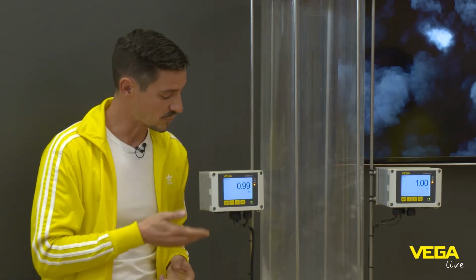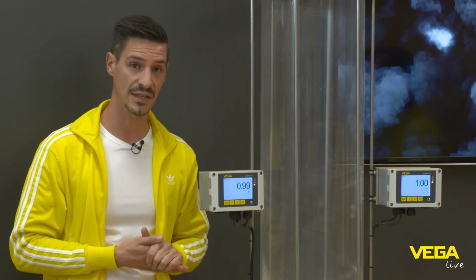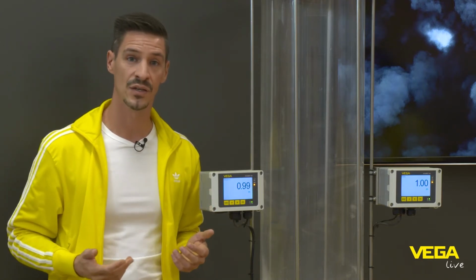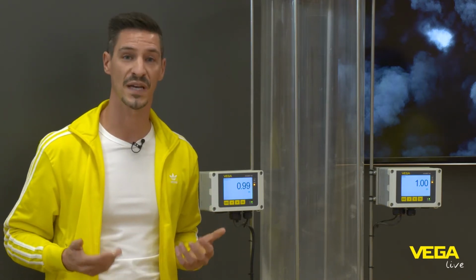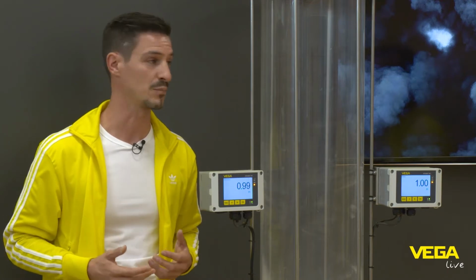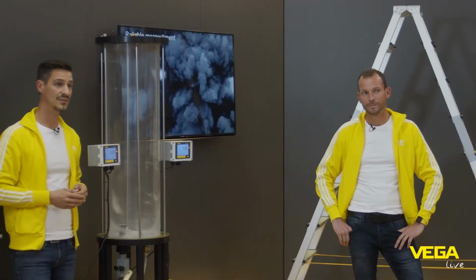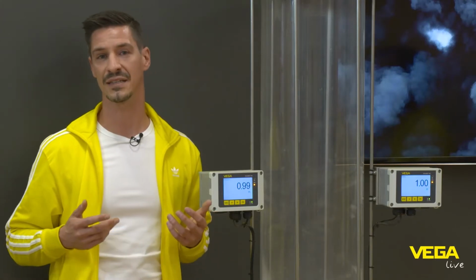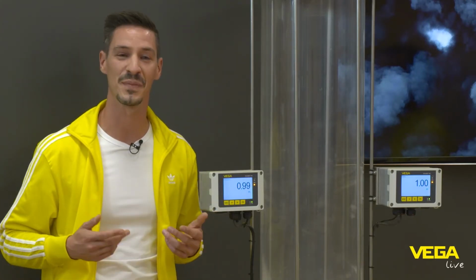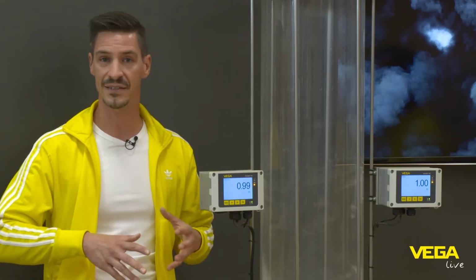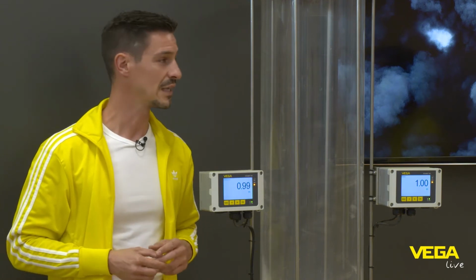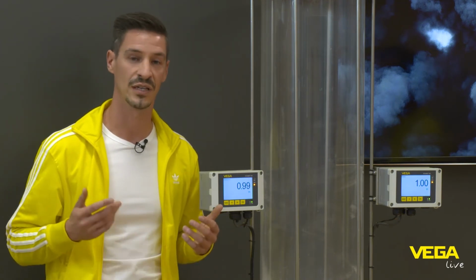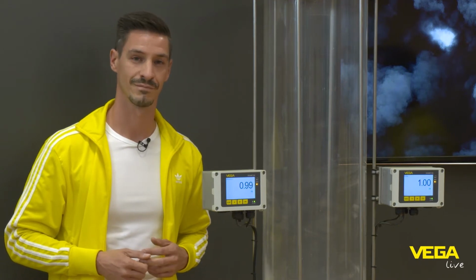This means we have a shift or a deviation of the measurement value, or in some cases, the complete energy will be damped away. So it's not possible anymore to measure with this device in a dust atmosphere. Compared to that, our radar device uses electromagnetic waves. These electromagnetic waves are completely independent of these kinds of influencing factors. Therefore, radar has an absolute advantage in a dust atmosphere.